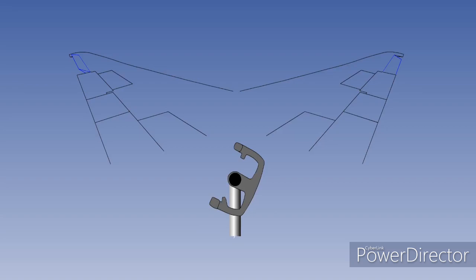If you were to hold the ailerons displaced from neutral like this, the left rolling moment would still exist and the aircraft would continue to roll to the left about the longitudinal axis. In normal flight, not something you would want to happen. Clearly then, ailerons are not a displacement control like the elevator. Ailerons are a rate control. If ailerons are displaced from neutral only slightly, the aircraft will roll slowly. The greater the aileron displacement, the greater the rate of roll.